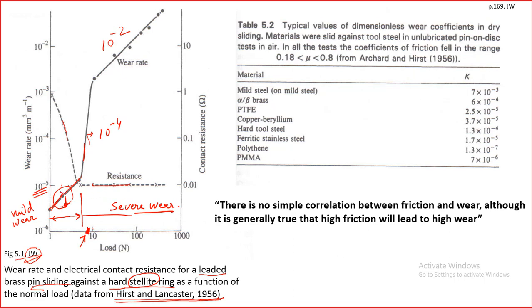Naturally it gives a smoother surface, and the debris is extremely small, typically 100 nanometer. So the size of the debris material is in the range of 100 nanometer. It is very small, and that's why when you do polishing, you cannot actually pick up the wear debris. It is there, in the liquid that you use, but it is very small.